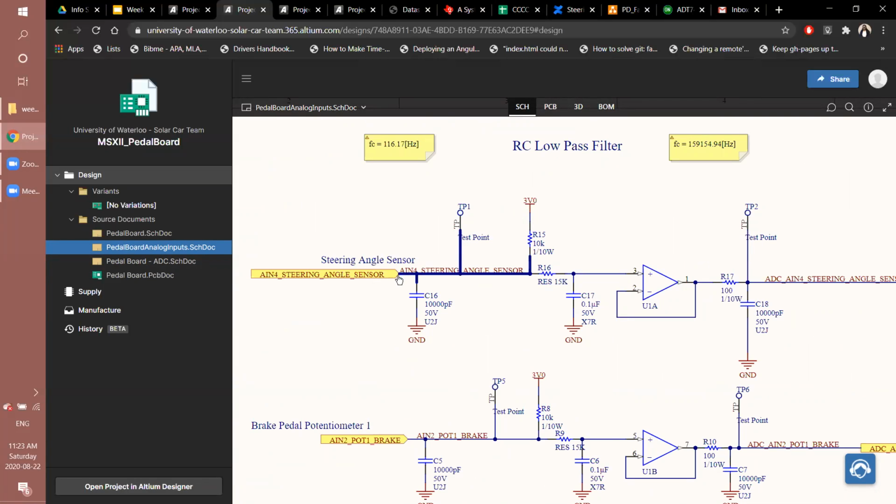So this is okay. Our potentiometer is a variable resistor, right? Honestly, we could have used 3V3 for this as well, but we use 3V0, and it's essentially part of the resistor divider that will give us an input when we change the value of the variable resistor that's the potentiometer. Does that make sense?